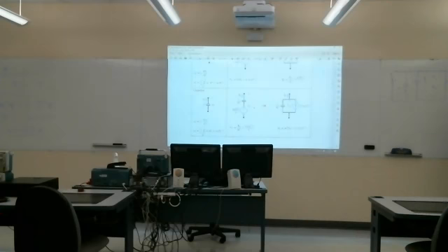It's going to be my voltage divided by 0.8S. So my S's cancel. 24 divided by 0.8, what is that? 30 over S squared plus 4S plus 5. Okay, so here's my current in the Laplace domain.